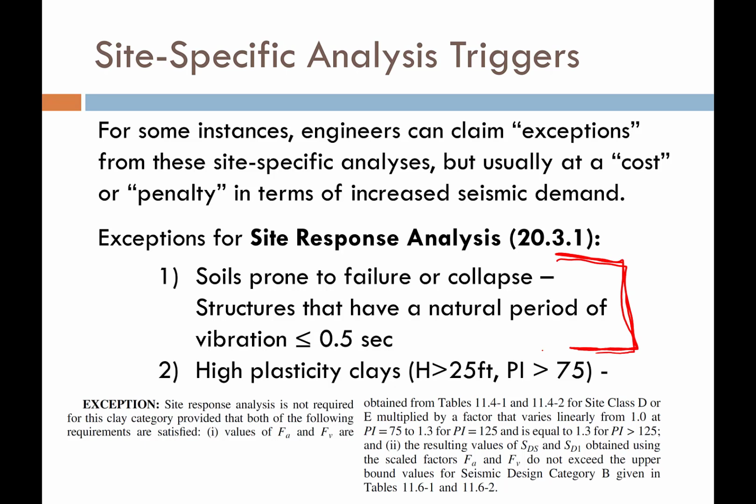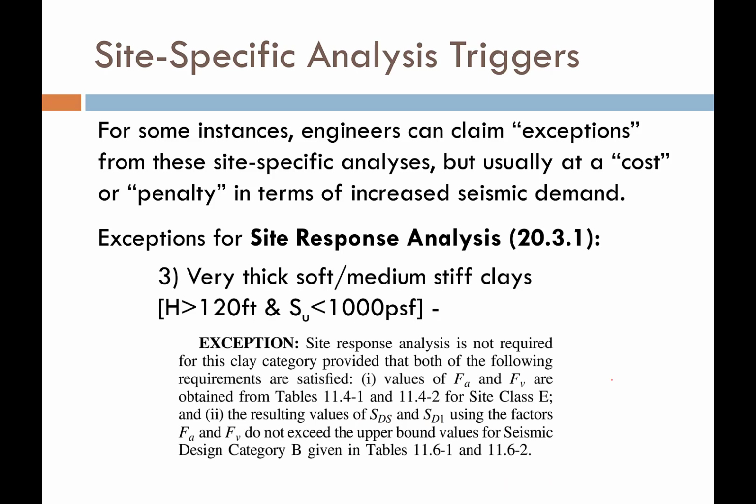A structure maybe 4 stories and or shorter, very stiff, and you have liquefiable soils or soils that are prone to failure or collapse. If that's the case, you can claim an exception and get back to doing a generic procedure with a penalty included. For high plasticity clays, we talked briefly about that exception, and then also for very thick and soft or medium stiff clays, a similar exception, a little more technical than I want to delve into for the purpose of this discussion, but there is an exception there.